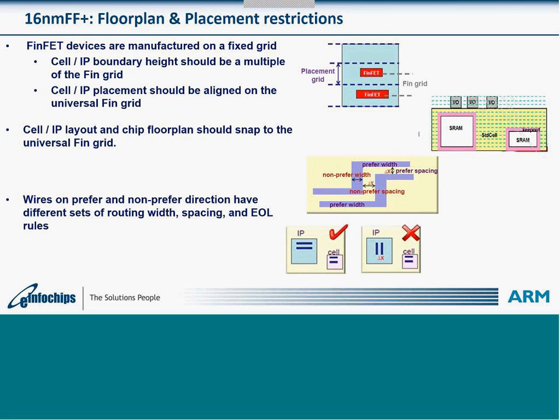Now everything on a chip, if we take M4 again, if we choose horizontal as the preferred direction, then even IP, SerDes, PLL, or anything else has to have that M4 preferred direction as horizontal. So this is a big impact on the designers as well, and especially on layout designers.